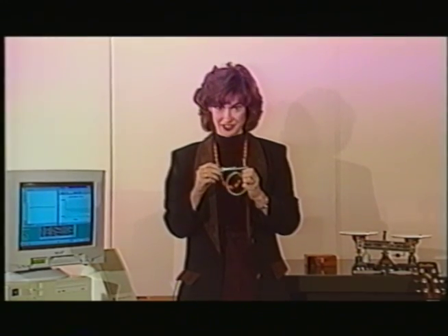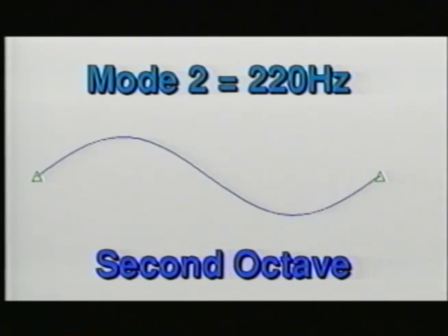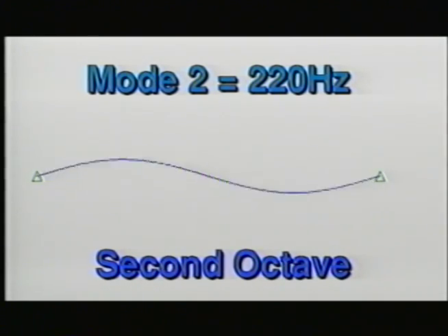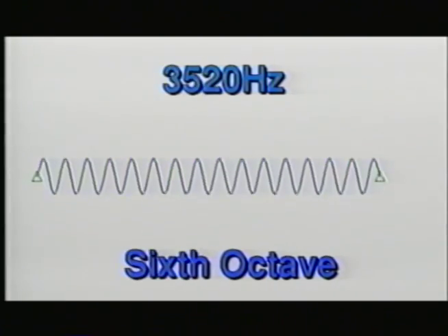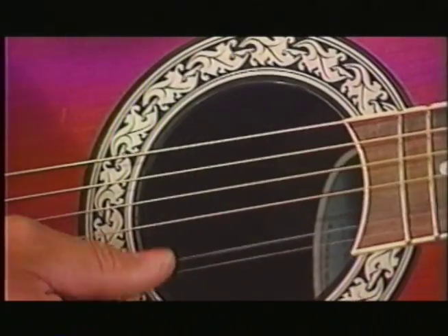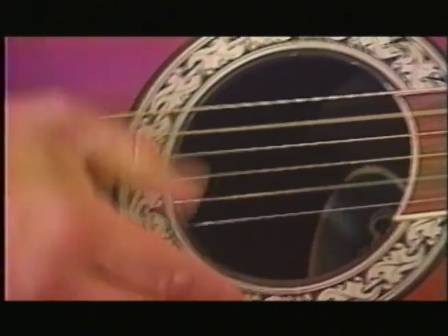Now we can plug the data we have gathered into the load stiffening module, which predicts the first vibration mode at 110 hertz. The correct result. Note that the second mode is 1 musical octave higher at 220 hertz, and so on up the musical scale. AccuPack Nonlinear Analysis Extender is the second way to predict frequencies as a result of load stiffening.